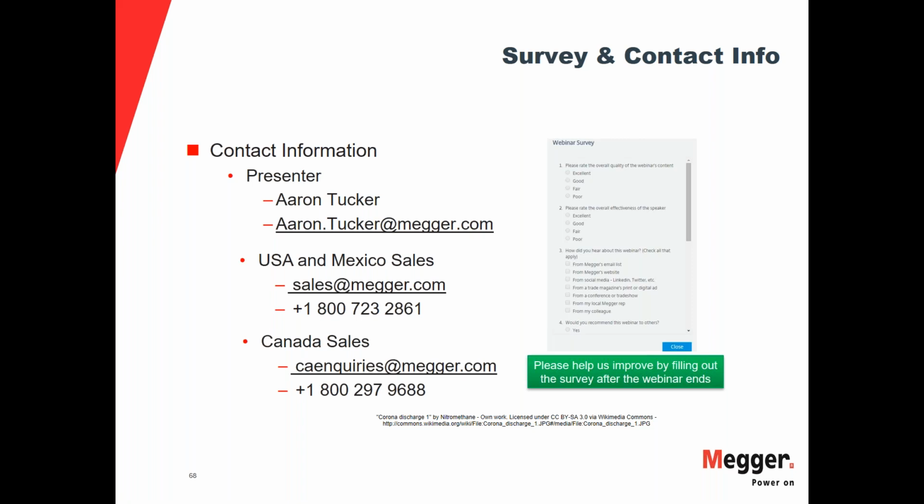So unfortunately, when there's nothing available, no nameplate information, you can look at your connections and base it off of your knowledge or your experience, if the connections are even marked. You can use that as an example and test it that way. Another thing is, even with, let's say, a pole type mount transformer, it has oil in it, but you can open it up and verify the connections inside.